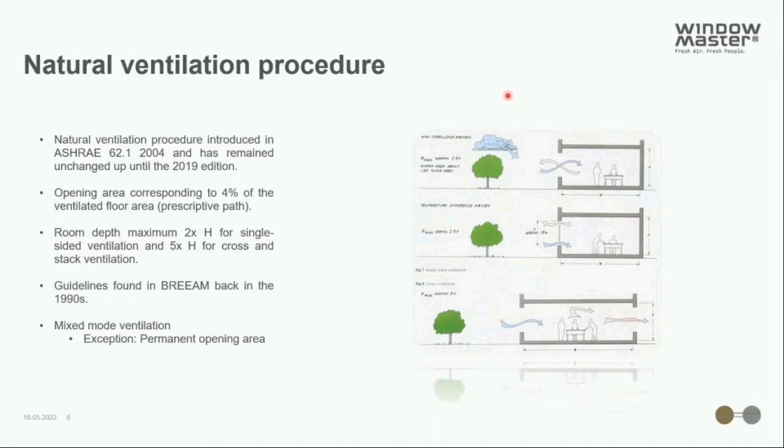However, a permanent opening area would not be very energy efficient. Or you can have controls that make sure the windows are not closed during the occupied hours. However, this doesn't really allow for a lot of occupant personal control, which is often a great benefit of natural ventilation.